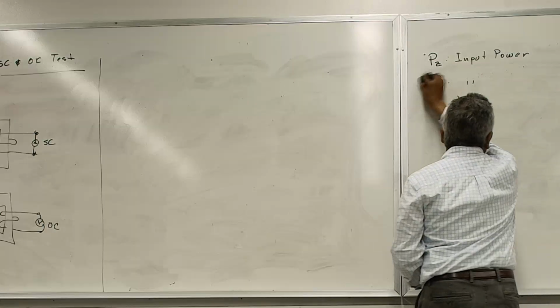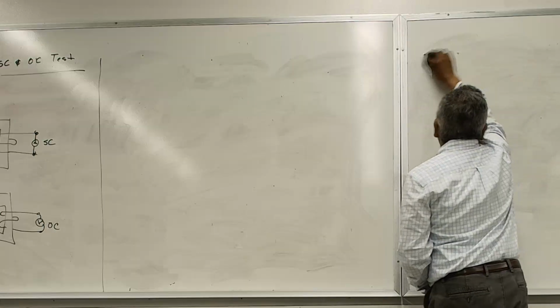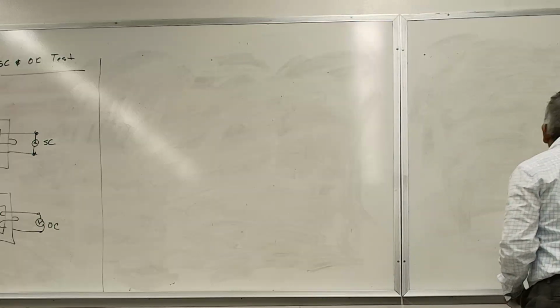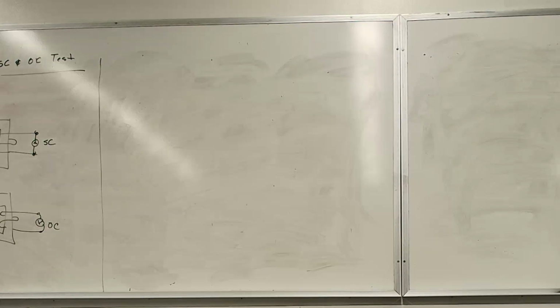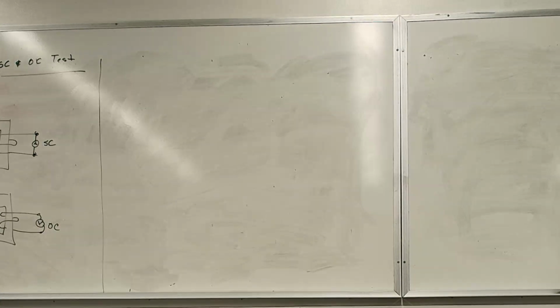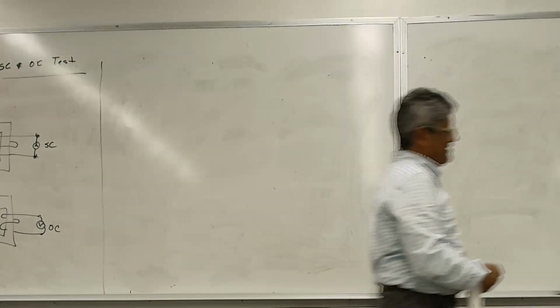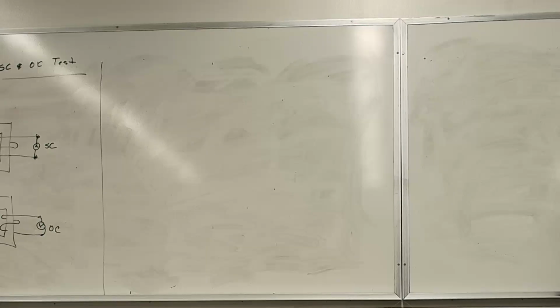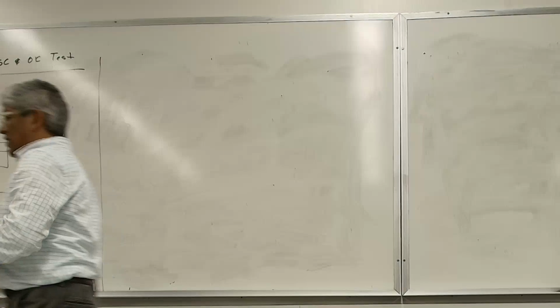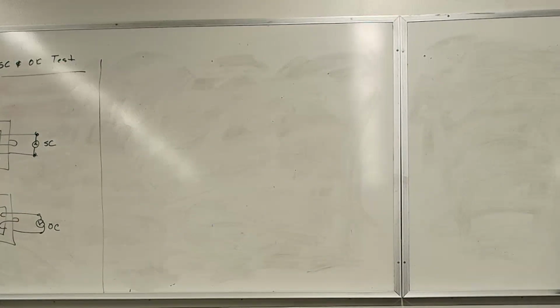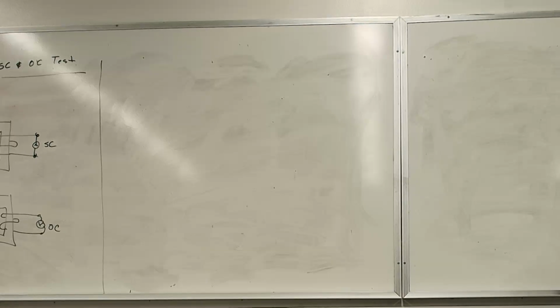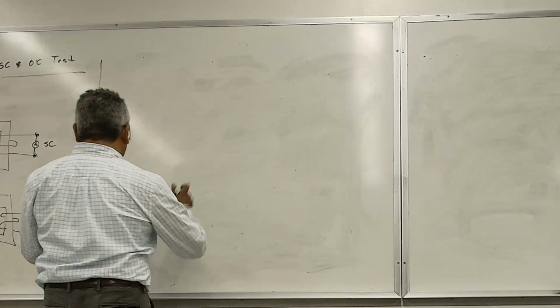As a matter of fact, I'm going to say 95% of the analysis that you'll do, that's all you need. But what are we missing? We're missing one branch. The flux. The excitation branch, right? Remember? So we have a branch that is here. To get the parameters for the excitation branch, that's when we use the open circuit test.